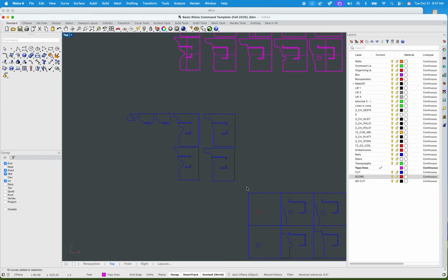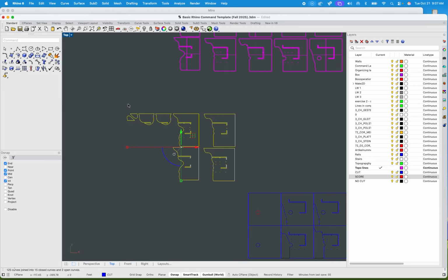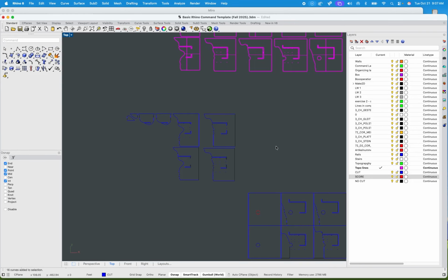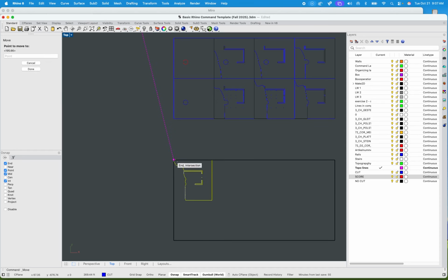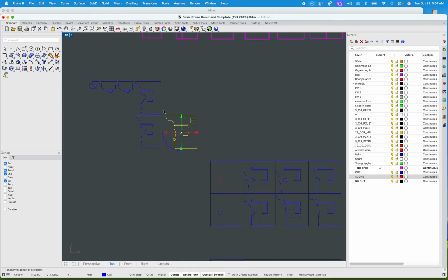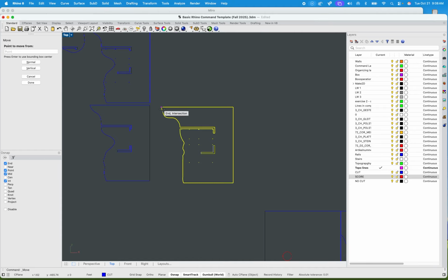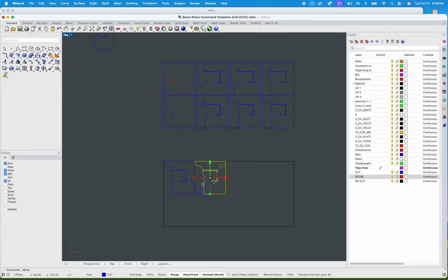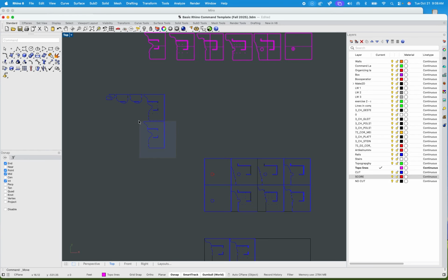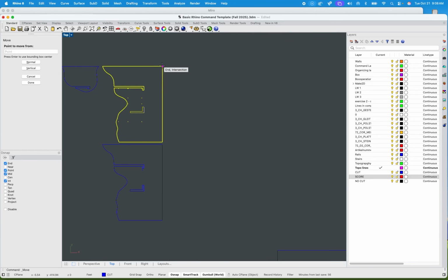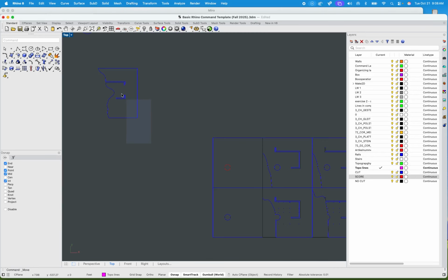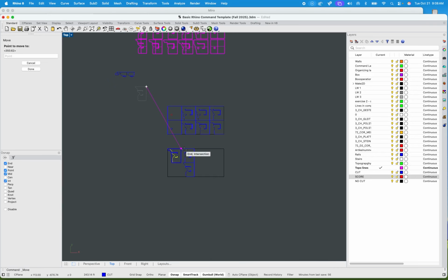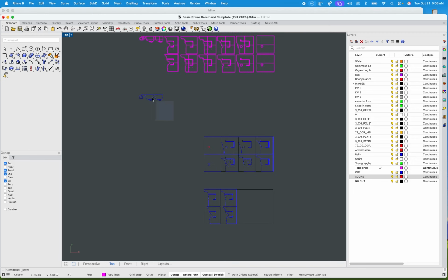But for the sake of it, let's join these back together. That way I don't accidentally lose some pieces. I guess I should have done that to the first one. But you could also group them again. Group doesn't affect the laser cutter, so you should be okay there. So if you do want to group each of these pieces, say one at a time, that way you don't move or accidentally skew all the little holes that we're going to make. Definitely good. You'll see what happens when you accidentally skew those holes. That one piece will be completely out of alignment with the rest, right? See, that's where near would actually come in handy there. Sometimes you do need near, not gonna lie.